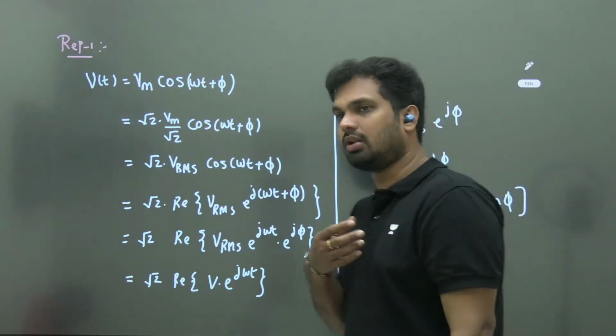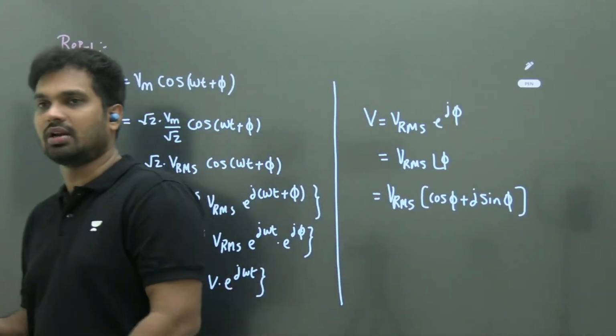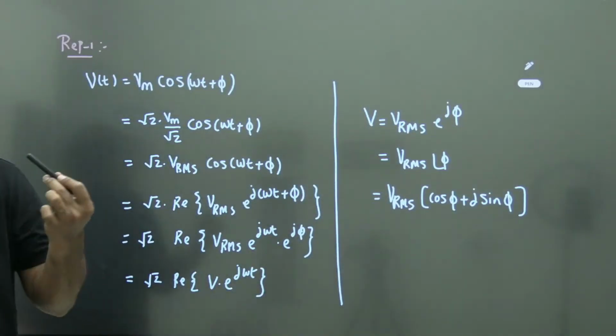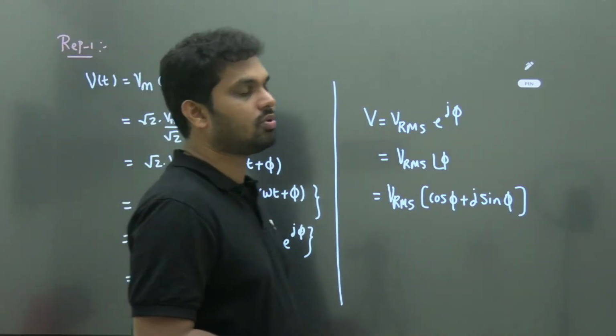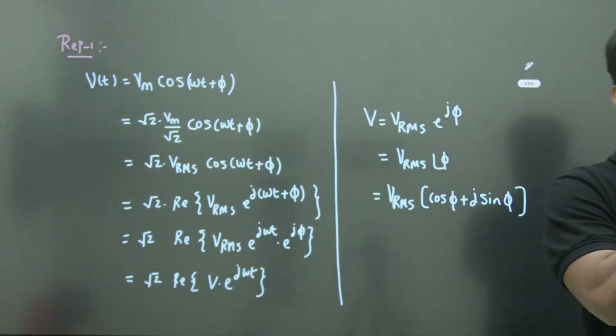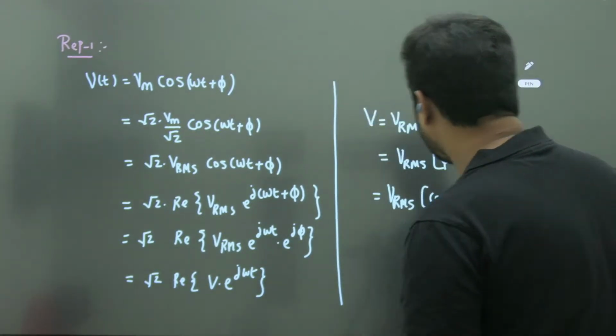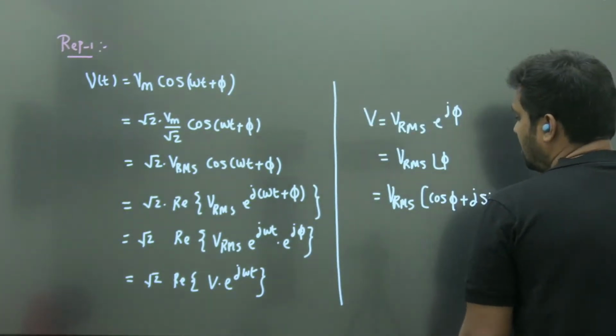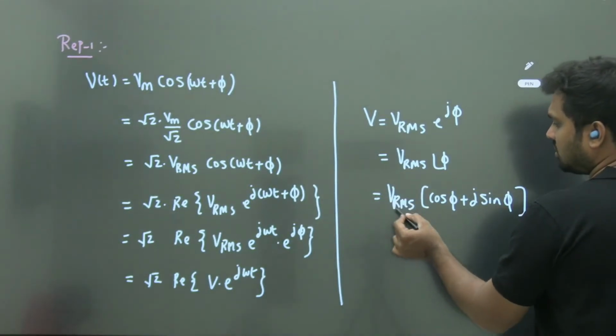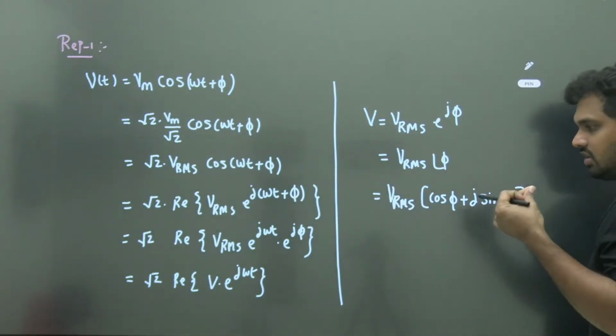When you are multiplying or dividing cosine or sinusoidal signals, we may use the exponential and polar form, which makes your analysis easy. If you are doing addition and subtraction, the rectangular form will be more helpful. So the RMS value is represented for the ease of convenience.